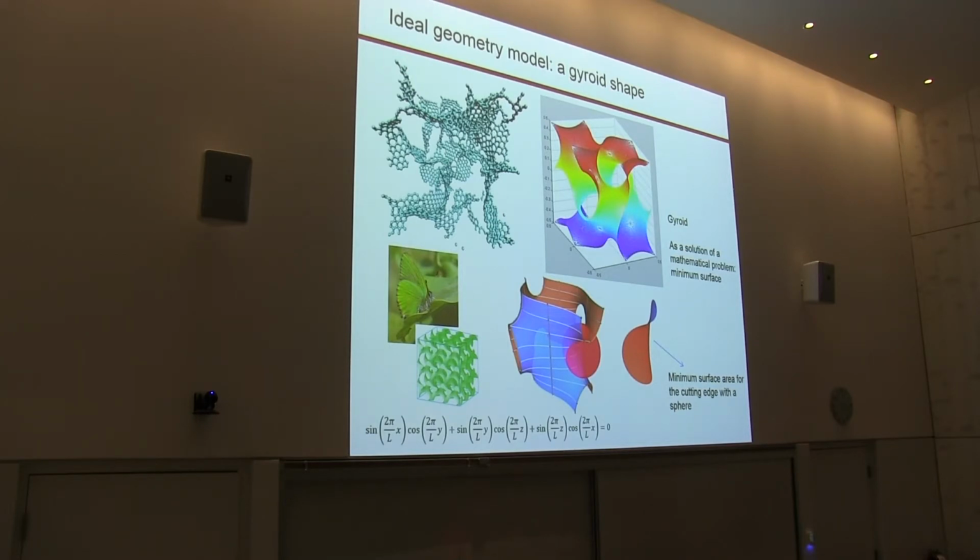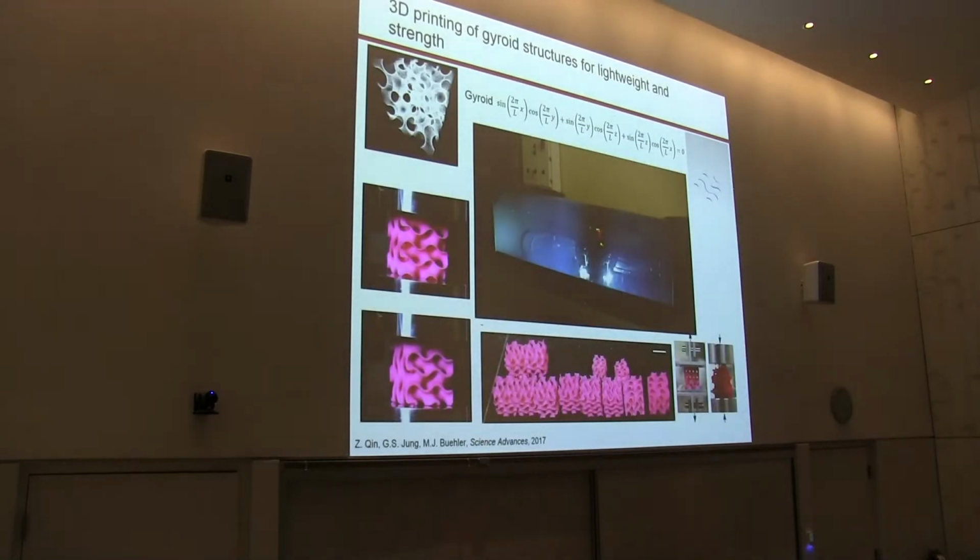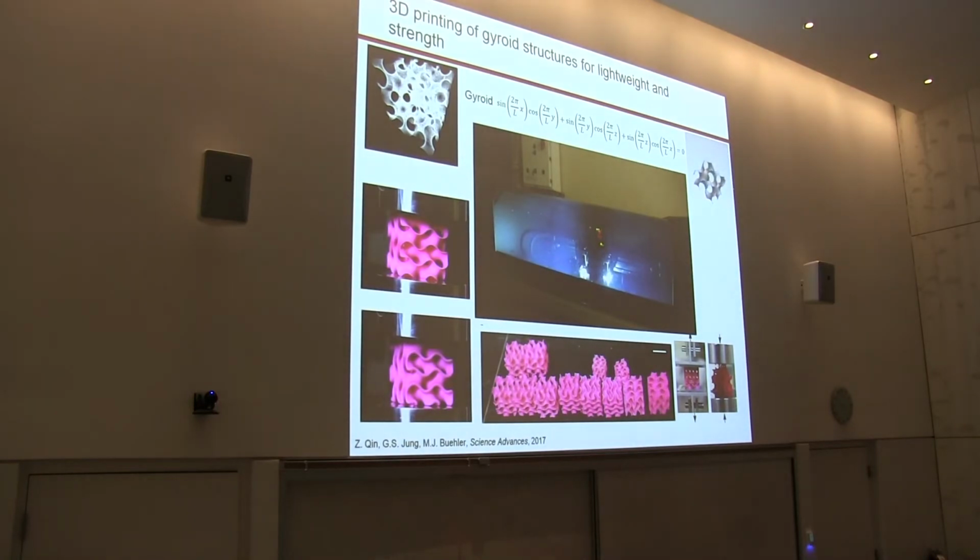And then, to validate and to say this geometry can describe this material very well, I use the help of a 3D printer. I use this mathematical geometry to form a data cloud and build a surface from the data cloud, and then I extrude the surface to a certain thickness to define a 3D geometry.